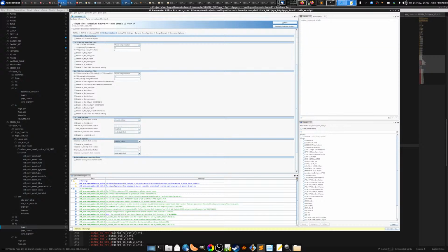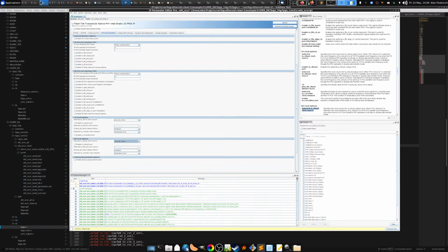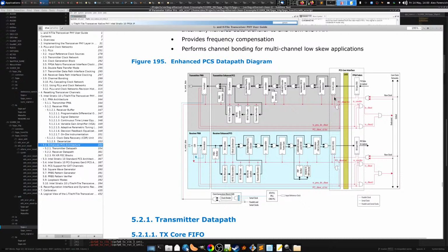So one thing that I need to do is actually take advantage of these FIFOs. There's a couple different clocking paths that are set up inside of these transceivers. We'll just take the RX path, for example. The data comes in here, the CDR recovers the clock, the deserializer then deserializes it. So you get 1 bit wide coming in here at line rate. You get 64 bits coming out here at line rate over 64. Makes sense, right? This is a high-speed clock. This is the divided serial clock. In this case, this would be like 161 megahertz at 64 bits.